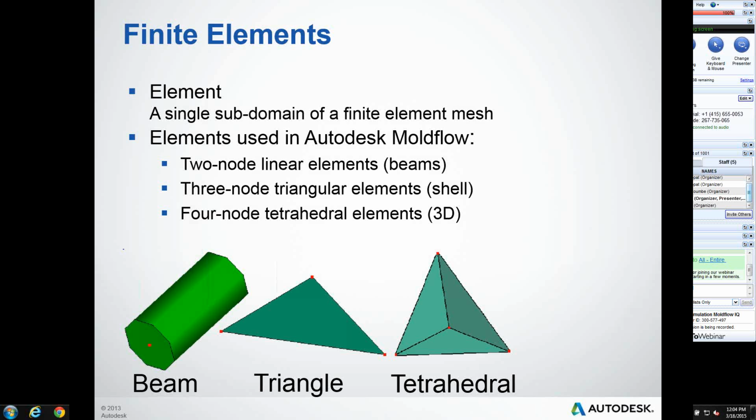The triangular element, which is a shell representation of the model, gives us a fairly good representation of what's going on. It allows us to apply thickness as an attribute versus representing the entire volume, though there are some caveats around the model itself. The three-dimensional style element allows us to represent basically any type of format.